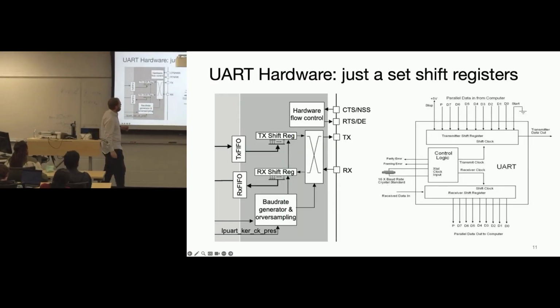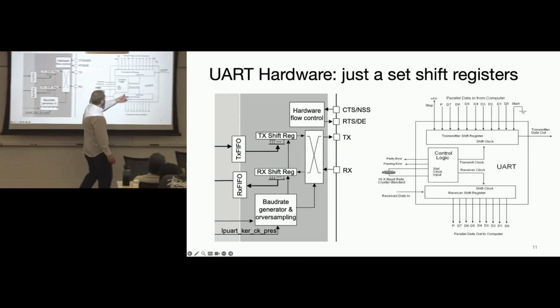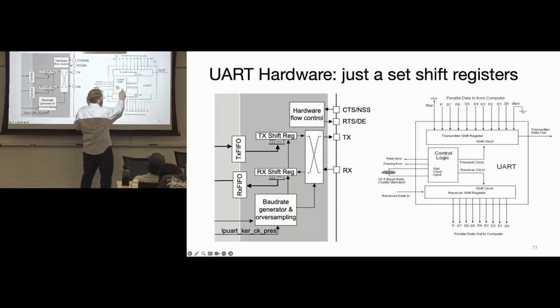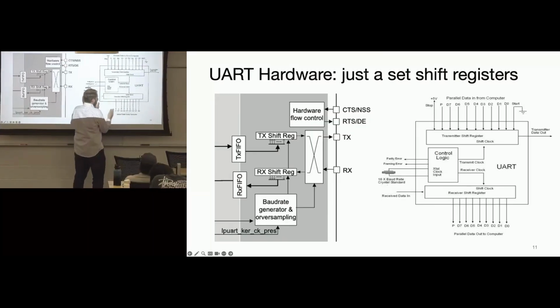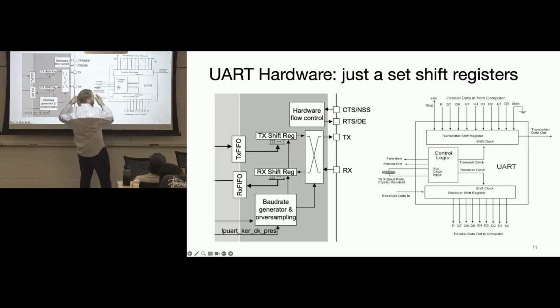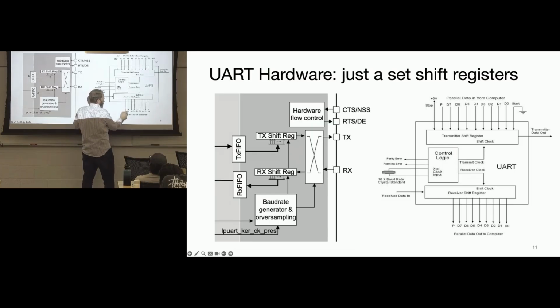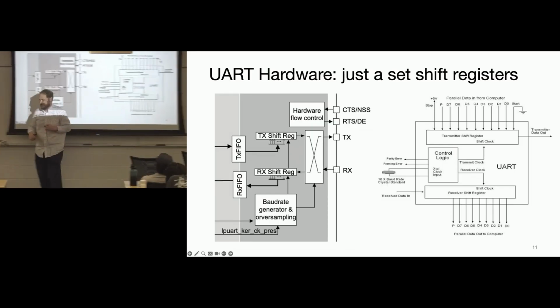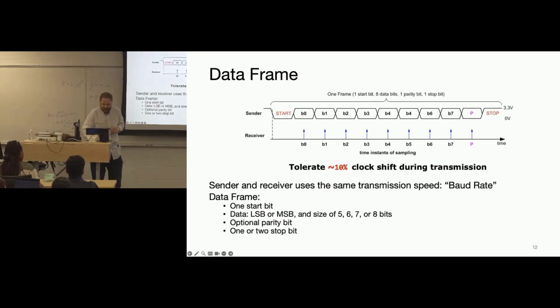That's essentially just a bunch of shift registers with a clock to keep track of when to time things in. This is where you agree on timing back and forth, so you literally have to program into your microcontroller: this is my baud rate, or my symbol rate, of how fast data should be coming in. Then you still need a way to figure out when exactly in time to latch in that data. And so how they do that